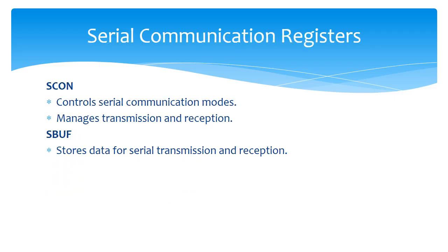And you have the next registers called the serial communication registers. These serial communication registers will send the data bit by bit. For example, when you are transmitting data from a parallel register to a device which can communicate serially, you need to have a parallel to serial shift register which will convert all these parallel bits to serial. It's the simple digital circuit you have studied, a parallel to serial shift register. So all the data will be transmitted through the serial communication pins. Similarly, the data also will be received through the serial communication pin. So transmission and reception can happen.